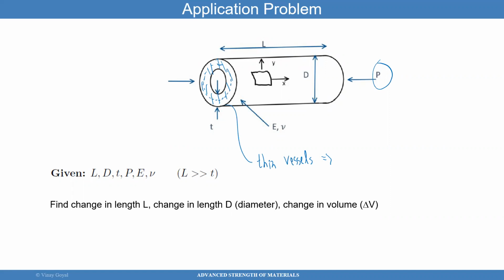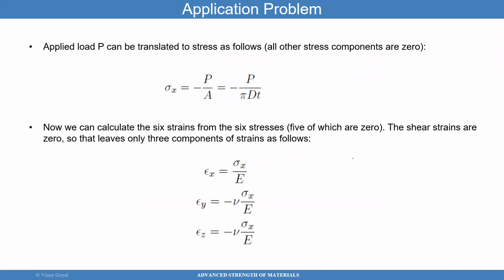But it's so thin anyway that you can just say that the perimeter is pi d, and if you multiply by the thickness, that gives you a very good approximation for area. And I should have used d uppercase. So that's true for thin vessels. You can just use that formula, pi dt that you see there. So very good for thin vessels, and it works well.